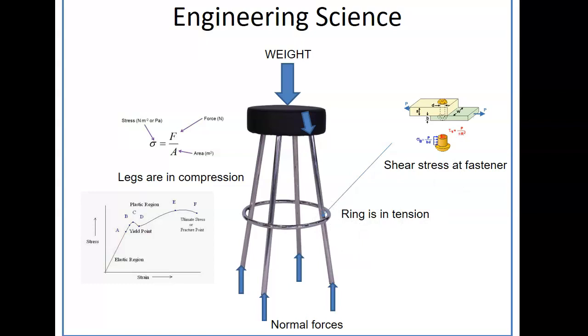I got to help assemble some chairs for a sound booth, and someone put the rings on upside down for the mount, so the screws were on top instead of coming from underneath. And what it meant is that instead of when people stand on top of the ring, it pushes down onto the frame held in place by the screw. When you put that upside down, now all the weight is held only by the screw, and so it was not going to be very sturdy, nor would it last very long. So that's just placement of things can make a really big difference.